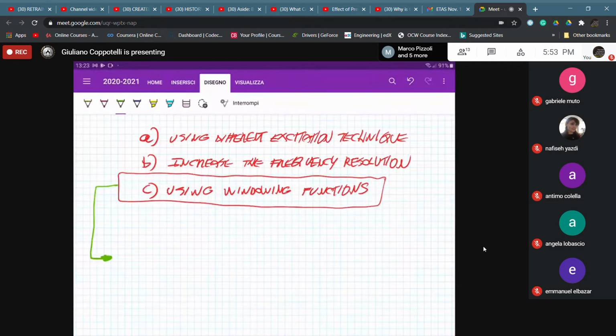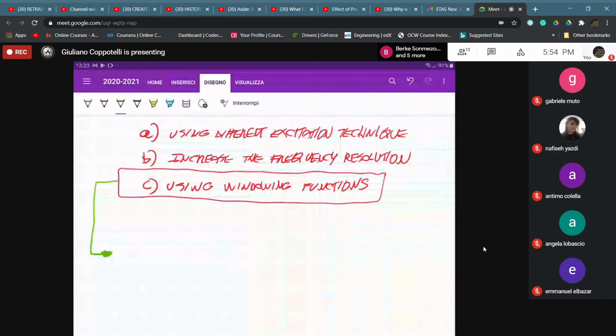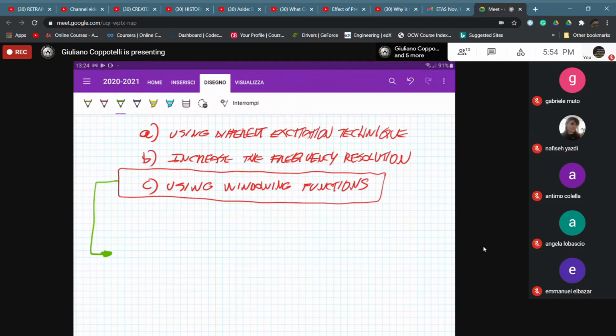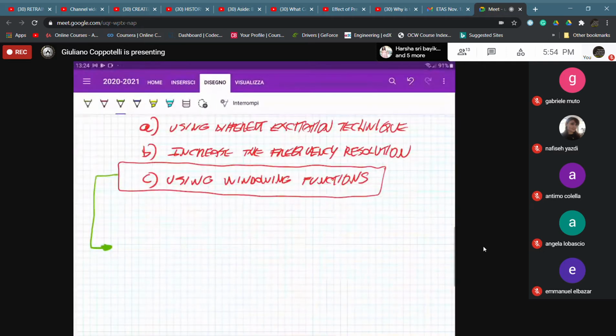Okay, if you go back to your notes and see what happens when you are having whatever sine wave, but is not observed with the right time, what you're having is, once you periodize your measurement, you can see that by moving from one period of observation time to the next one, there is a discontinuity. So the windowing functions are just reducing these discontinuities.